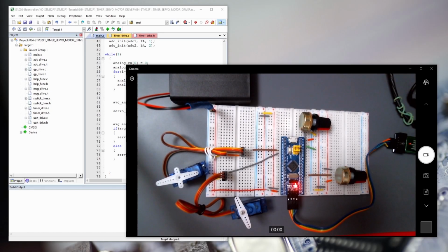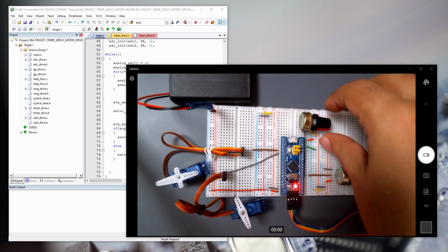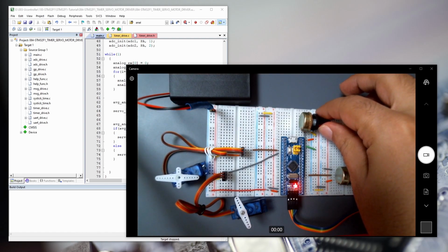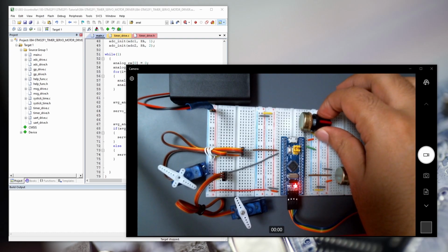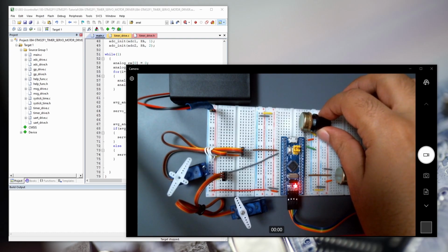Hi everybody, welcome back to this new WeeW tutorial for the STM32F1 timers, and this time we are going to create a driver for the servo motor. And we do have a normal servo motor which is controlled by position, as I will do here. So as soon as I move my potentiometer, this one will smoothly follow the direction that I'm putting.